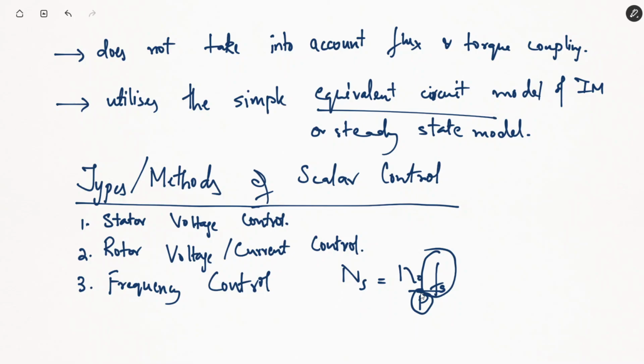सिंक्रोनस स्पीड कम होने का मतलब है कि आपकी रोटर स्पीड भी कम हो जाएगी, ठीक है. The rotor speed will always be less than the synchronous speed of the induction motor. So if you are changing the synchronous speed, accordingly your rotor speed will also vary. So again, frequency control can be achieved either through power electronic devices, or you can use rotary machines to obtain frequency control.